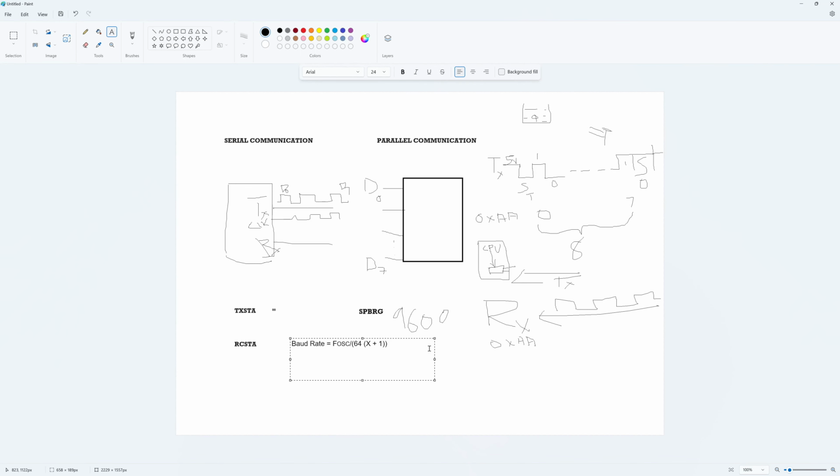We know the values also, right? The baud rate we need is 9600. There are many baud rates. It is an assignment kind of thing: you find out which baud rates are available in serial communication, UART communication. You can find many baud rates. This is the common baud rate where many devices are marketed with the default value. 9600 is the default value for many modems, many UART based communication devices.